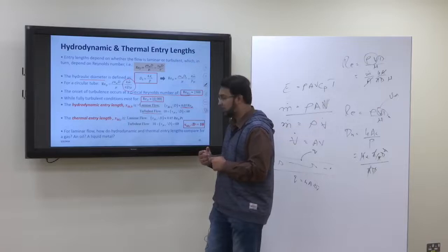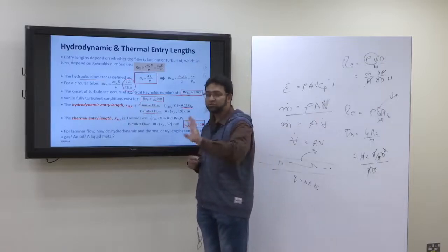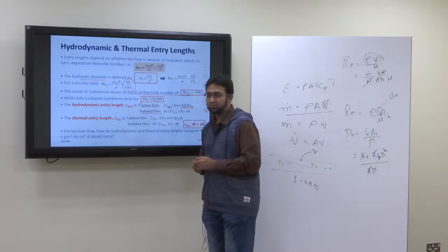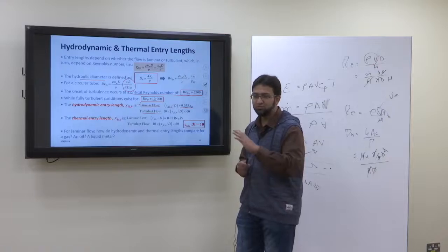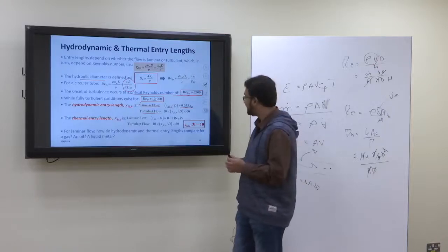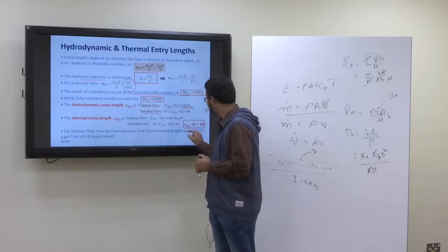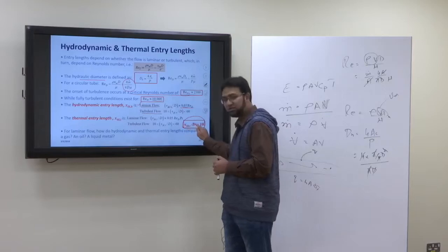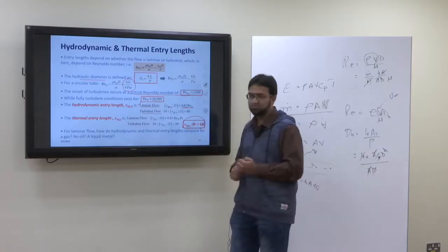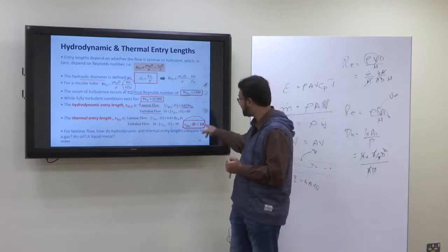If it is the turbulent case, then we do not use the Reynolds number. Then the formula is x_FD by D is equal to 10. I just need to know the diameter, and multiply the diameter by 10.